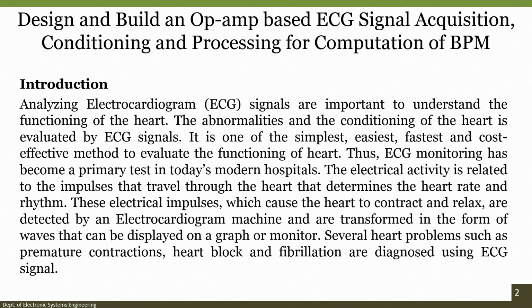So, we are going to design and build an op-amp based ECG signal acquisition, conditioning and processing of the PQRS wave and compute BPM. The whole idea is that we will acquire the ECG signal, extract the QRS out of it, and calculate how many QRS peaks we are getting in a minute.